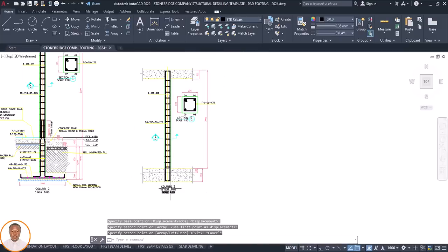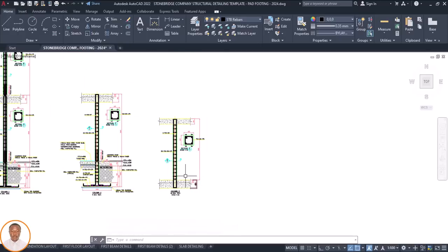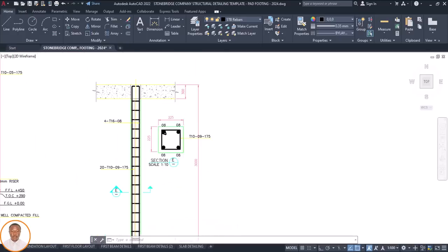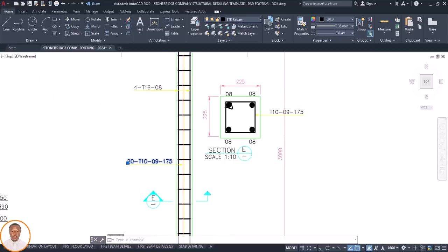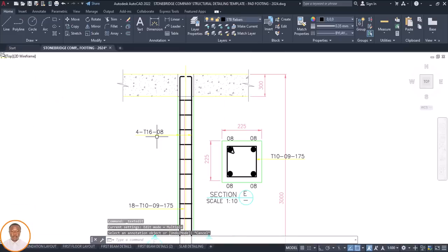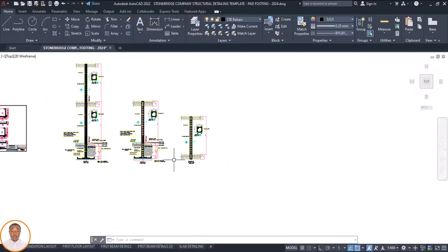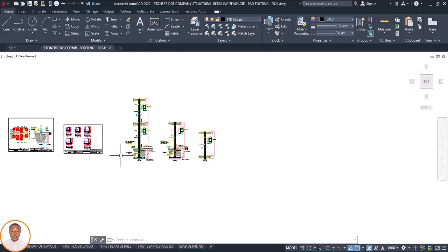All right, so once you have done this one again, check your beam depth. Is that okay? If it's 450, it's 450, so good and fine. So this one also, confirm this. Okay, and this one is 18. So I'll edit this one to 18, my link. It's still 4Y16. Okay, 300. Confirmed.